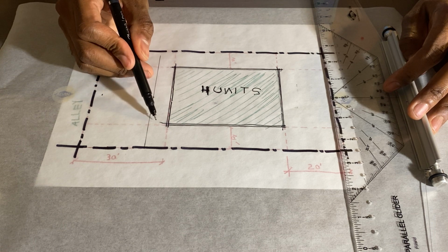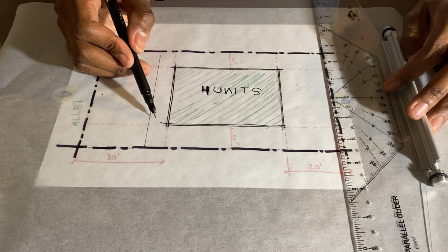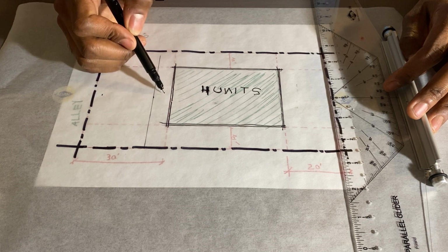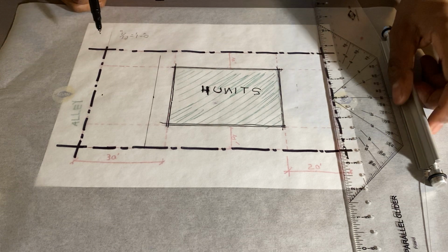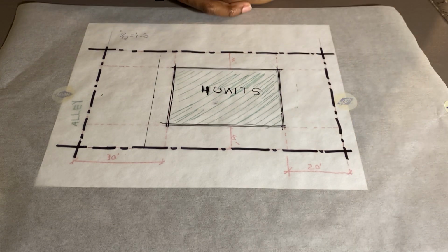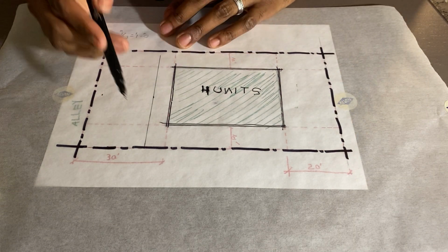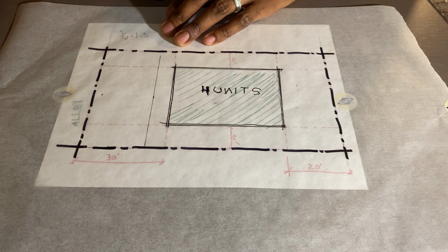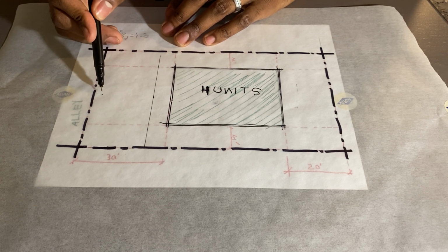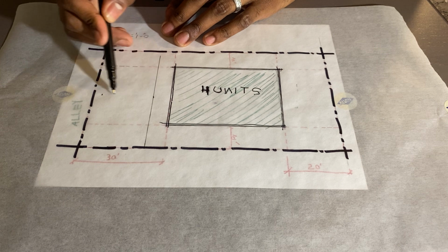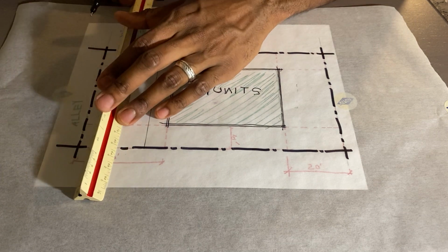You need a pathway that's ADA accessible, not only ADA accessible, but also fair housing accessible to get into the building for what's considered multifamily buildings. That's neither here nor there. Let's stay on task here. So we've got our typical 20-foot deep parking space measurement, just here.